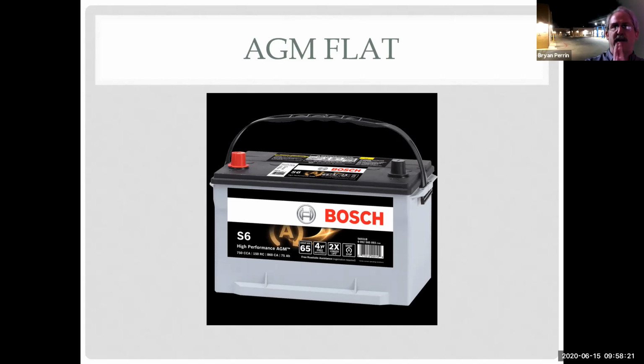So a lead acid battery on a normal car, when I crank the car, my voltage can go down as low as 9.6 volts. And when I start the car, it can go up as high as 15 volts. So we're talking a 5.5 volt range between when I'm cranking the car and when I'm charging it back up on a normal lead acid battery. My AGM batteries don't like to go below 11 volts cranking and really don't like to go above 13 volts charging. A 2 volt range. So you can imagine if I take this AGM and throw it in a car that's not designed for an AGM battery, the charging system's not going to control it right. It's going to cook this battery and it's not going to last as it should.